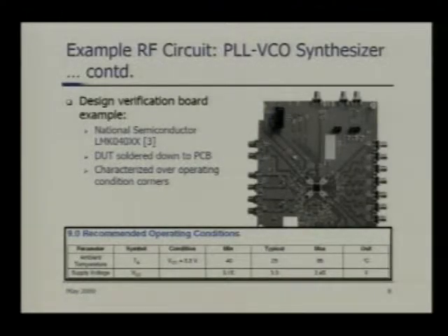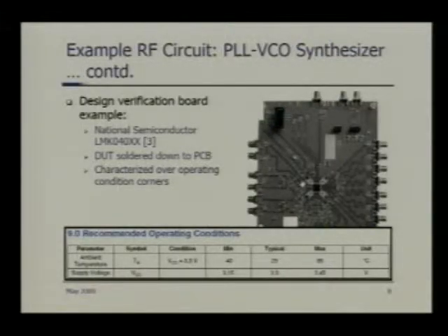The advantage of using the contactor is that, unlike a soldered down PCB, you can take the part out after you are done with the testing and put in another part, then a third part, and so on. But in the case of a soldered down PCB, for as many parts as you characterize, you should have as many test fixtures. So there is a cost issue.